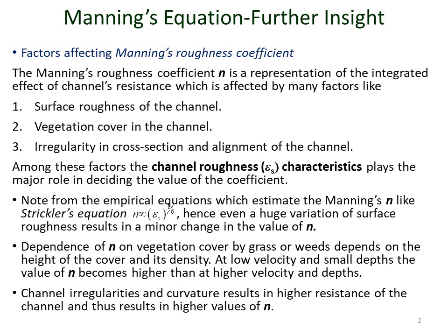The dependence of n on the vegetation cover is determined by the type of the vegetation. It may be grass, it may be small weeds. It also depends on the height of the vegetation, the cover and its density. All these factors have some influence on the value of n, and sometimes determining the actual influence of these factors on the value of n is complicated.